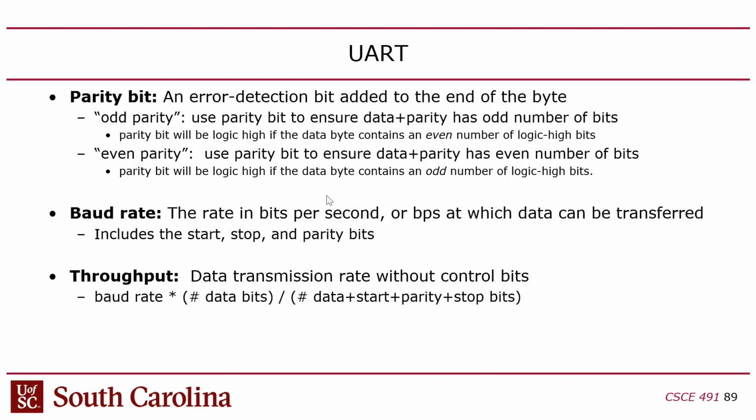Now you might say, well, sure, but that includes the start and stop bit too, right? No. You got to forget about those. Forget about the start and stop bits. They're not part of the parity. They're not part of the data, which again confuses things even more, because if you're looking at a timing diagram, you're going to see the start and stop bits, and you're going to see the data bits and the parity bits. And what are we counting here? You got to only count the bits in the data and the parity for the parity calculation. Forget about the start and stop. Those are only for control purposes. Okay? Yes?